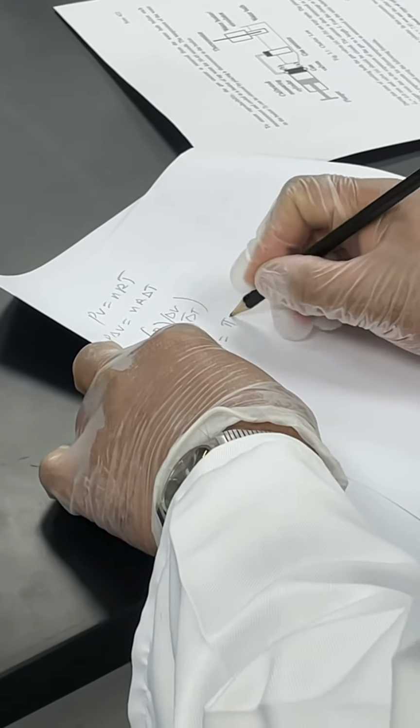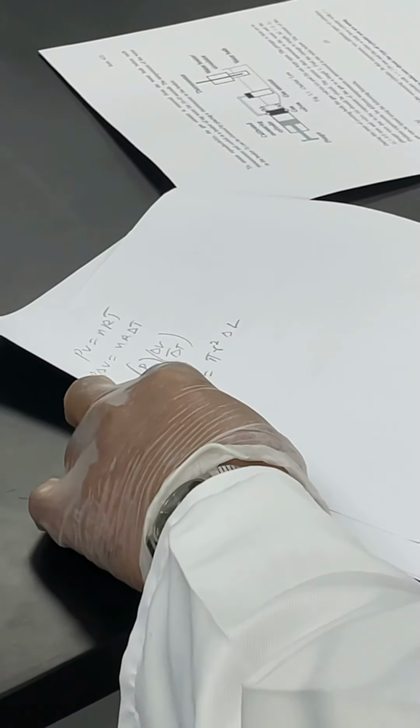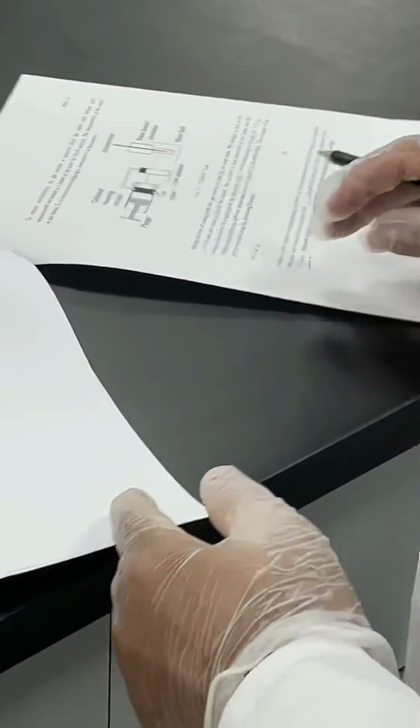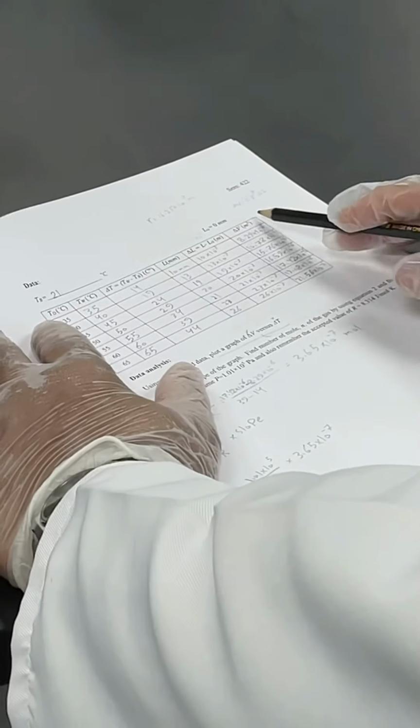How to get delta V? The delta V is equal to pi r square into delta L. R is the radius of the piston. This will be printed on the paper. What is the radius of the piston? That is given in millimeter. You have to convert into meter. And this is delta L. Can you get the volume here? Delta V, the change in the volume, you can fill it here. And see, the volume is a different number, 10 to the power of minus 6. Maintain the uniform power throughout this, so you can keep the power in the unit.